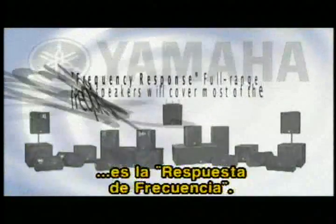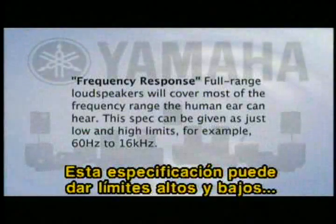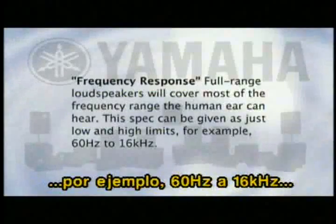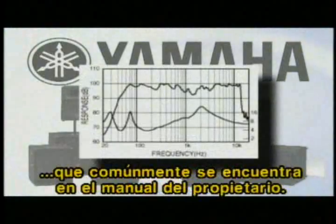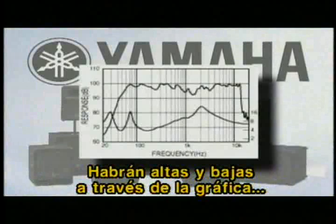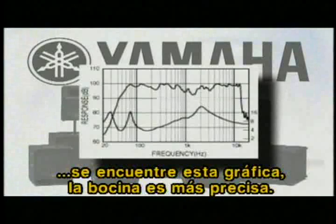The next specification to consider is frequency response. Full-range loudspeakers will cover most of the frequency range the human ear can hear. This spec can be given as just low and high limits. For example, 60 Hz to 16 kHz, which can be somewhat misleading. It is more helpful to see a graph or plot of the frequency response, usually found in the owner's manual. These graphs give a better idea of the performance of the loudspeaker. There will be peaks and dips along the graph to show the overall response. Generally, the smoother this graph or curve is, the more accurate the loudspeaker.